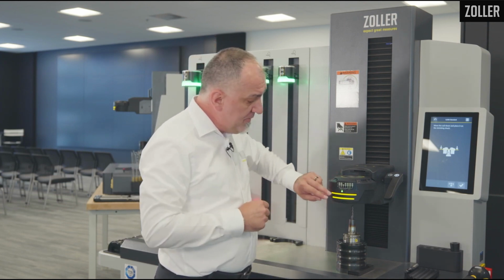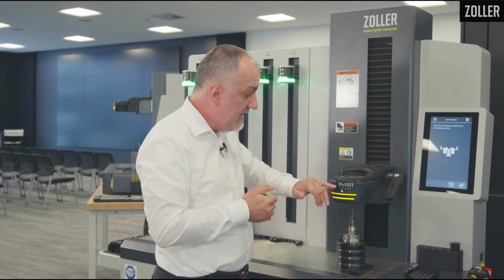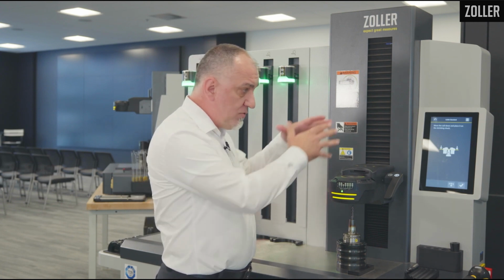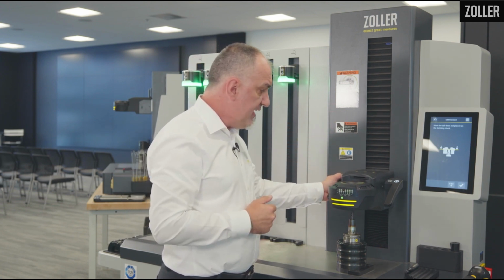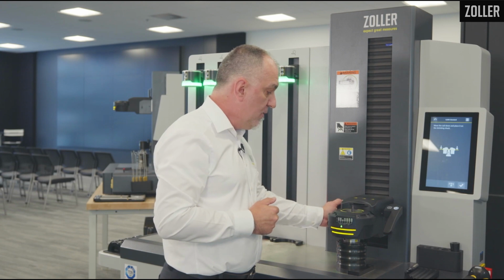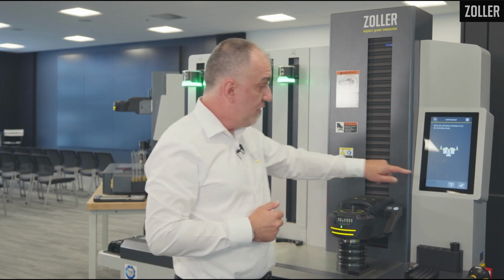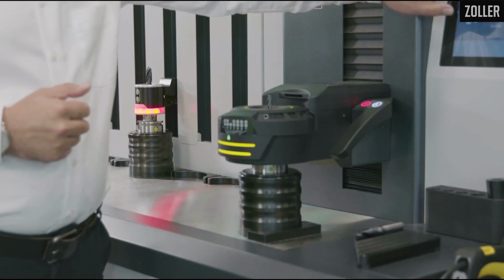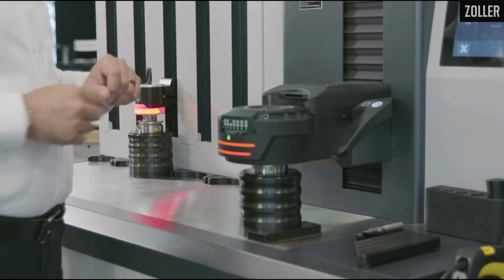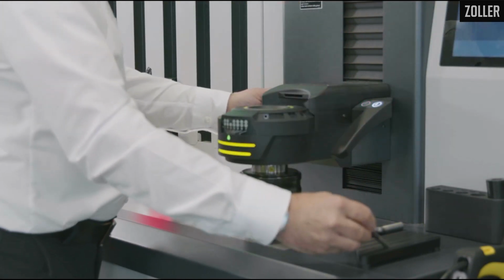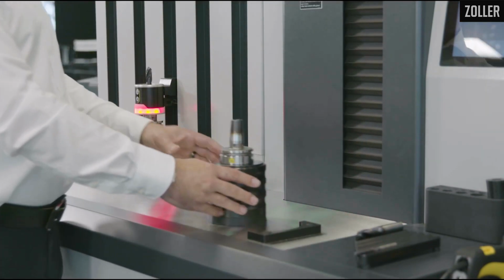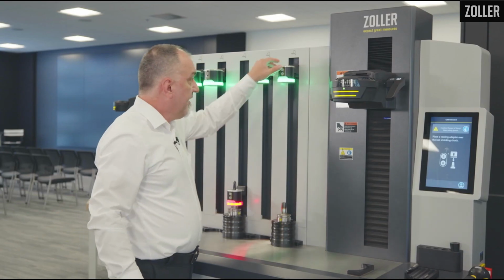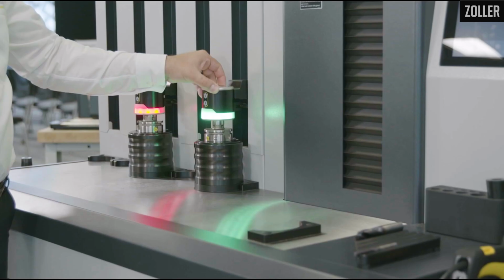As I mentioned in the beginning, here we have the coil. We have two windings that the system just chooses, because it's already pre-designed. It can go independently, one, or it can go both, and that's already assigned. In this case, I just bring it down to the position to unshrink the holder. I confirm it. In this case, I'm using the screen. I take the tool out, and again, the light is blinking green. I bring it down to cool it.